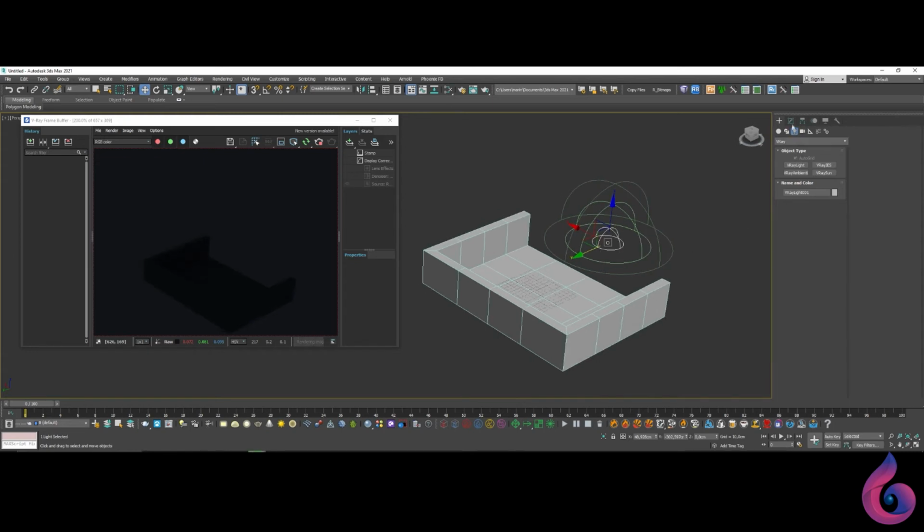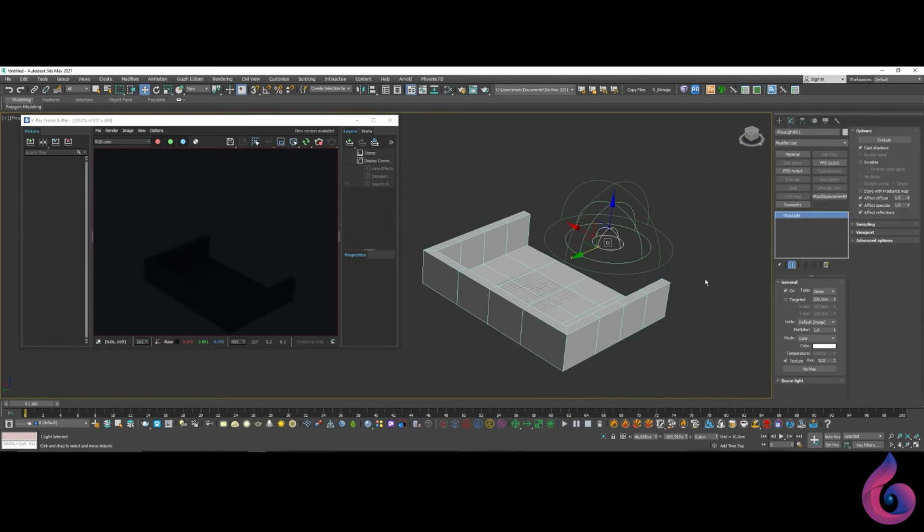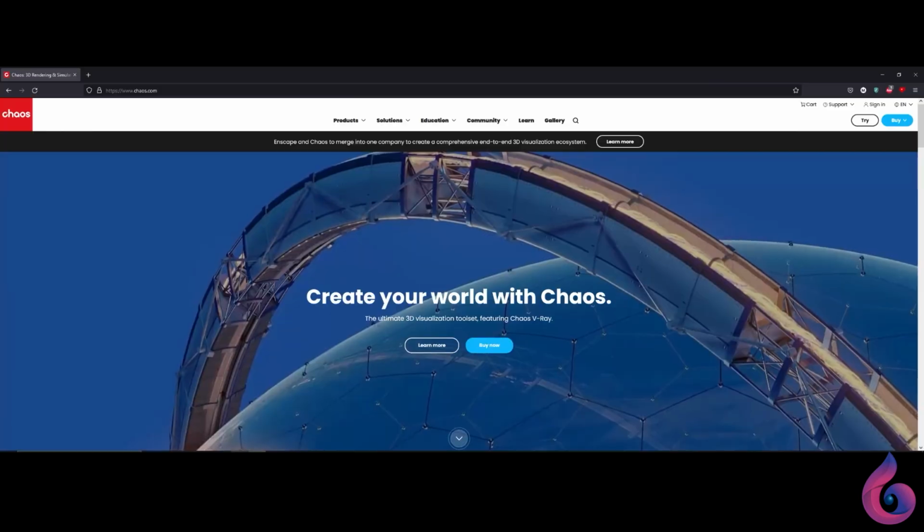The next way to illuminate objects is V-Ray Dome Light. With it you can use an image to illuminate the whole scene. From the site polyhaven.com, which is free, you can download HDRI spherical images and thus use real lighting to light up your stage.